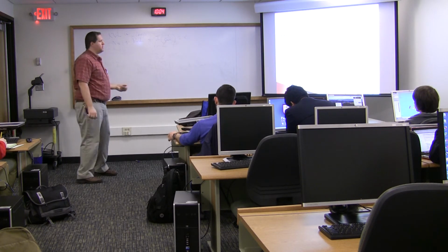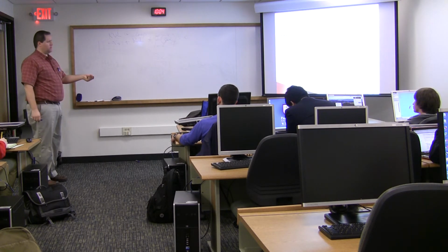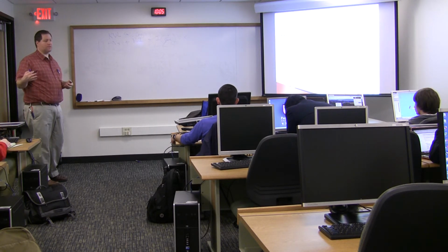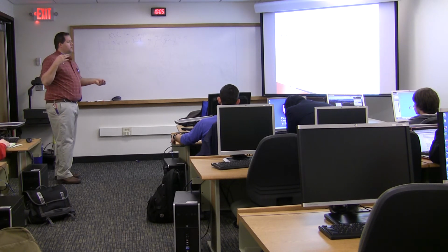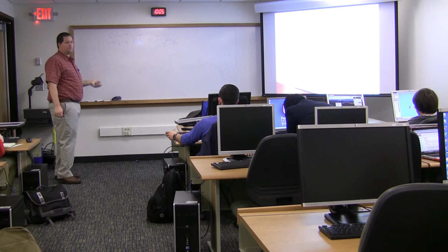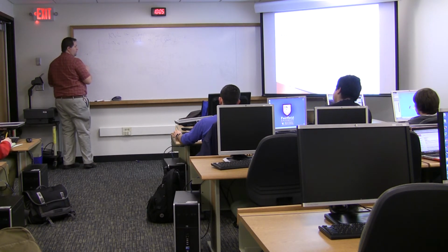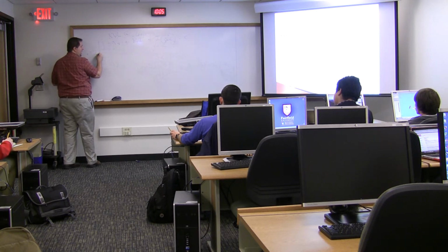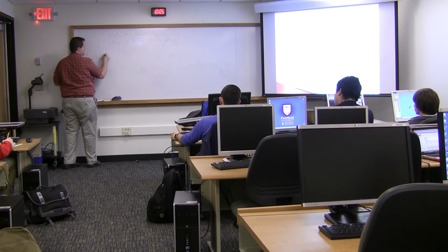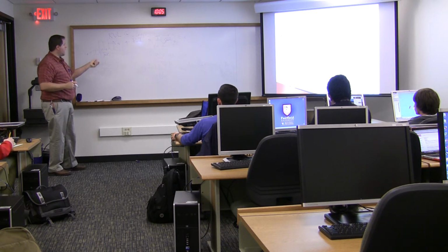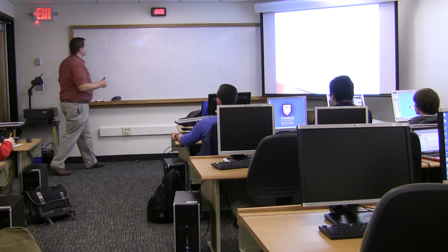And then when I'm done, though, I want to get Vout. So that's what it's asking me for. I want the transfer function Vout over Vs, a voltage gain transfer function. So the output voltage has to come from this current that I found, right? And so I can write that down. I know the output voltage is just going to be I times that 1 over j omega C, right? Once I find I.